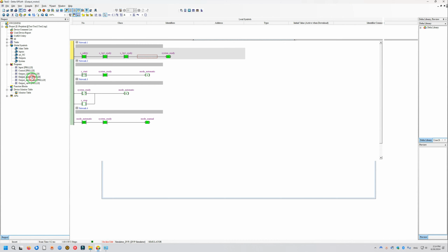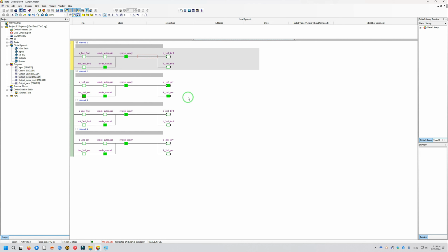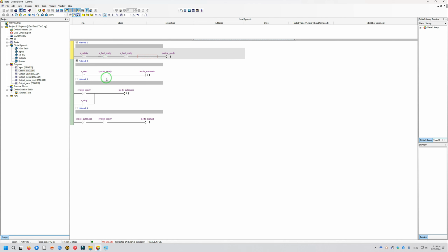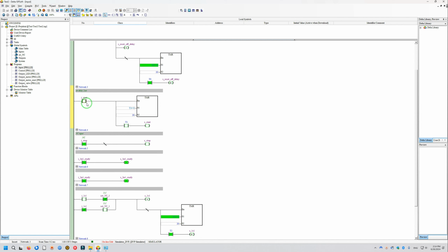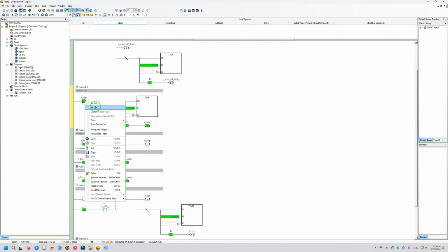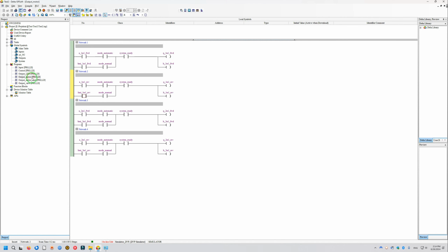So go here and you can see we can run the motor, but once we go to automatic mode, let's start it by pressing the start button. I have added a delay here. Okay, let's leave it now, but later I will delete it. Now you can see mode automatic is on, and if we go to our output motor subroutine, the motor is not running, even though this bit is on, because it is for manual mode.